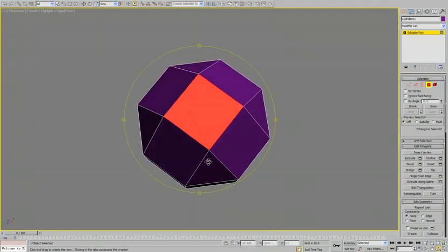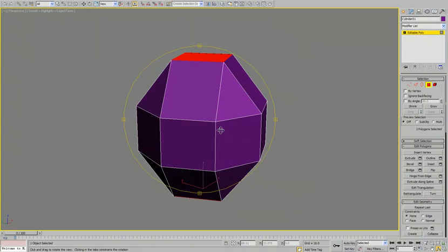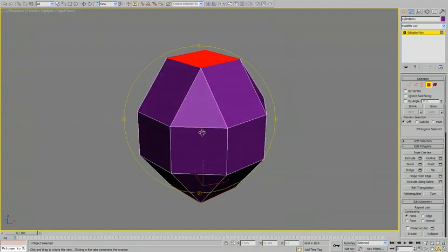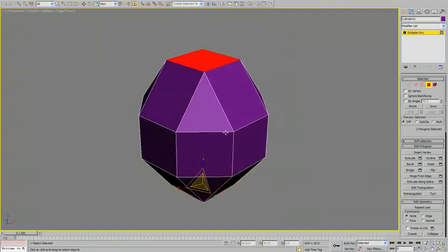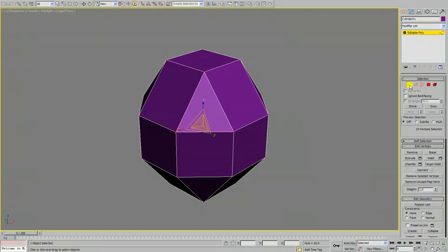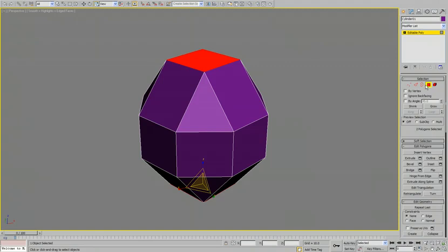Now we need to convert the selection of these polygons into a selection of vertices attached to them. So here you can see if I just simply try to switch to vertex submode, I still see this old selection of vertices. But if I go back to polygon submode and try to switch to vertex submode while holding the Control button on the keyboard, I will convert the selection of polygons into a selection of vertices attached to those polygons.